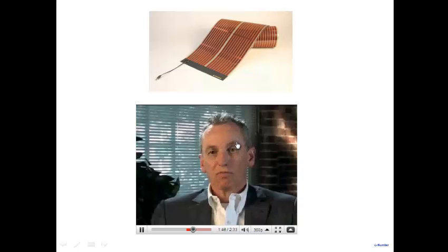So roll-to-roll printing for organic solar. So that's the idea. The other thing that is very interesting is that people have taken organic materials which are partly transparent, and they've made solar cells out of them on pieces of plastic with efficiencies of around 6 or 7%. As I said, typical commercial solar cells would have efficiency of 15 or 18%. So that's high. But then they've made them partially transparent. So you have an organic material which will absorb in the infrared region here, leaving a lot of visible light to come in. And so you have a transparent solar cell on a piece of plastic.